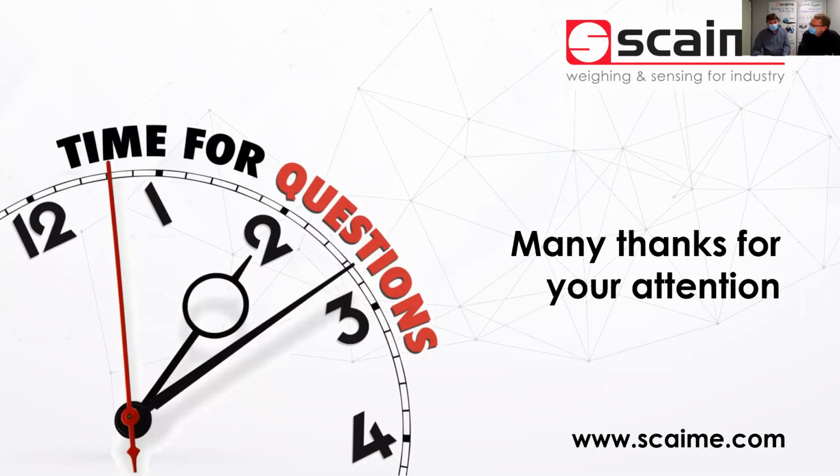Not to prevent this, but in case this happens, what we usually recommend for applications is to have a loop back from the last sensor to the interrogator. So an optical fiber comes back to the interrogator; it's not plugged in and not used if there is no problem. But in case of problem, we can have access to the sensors through the other side.